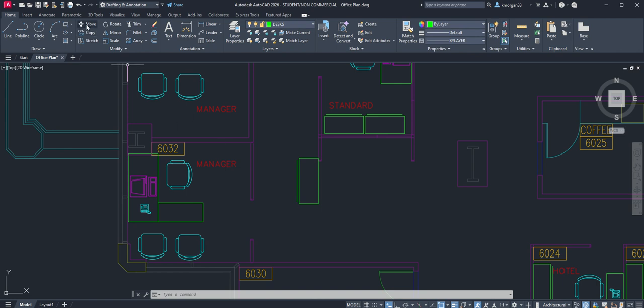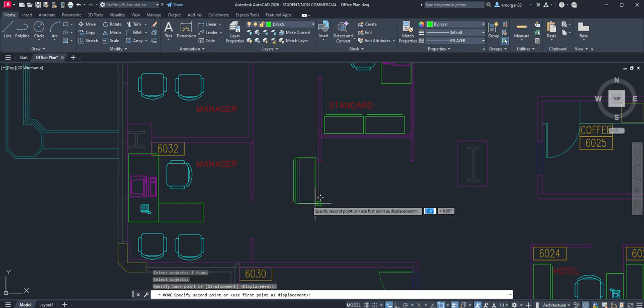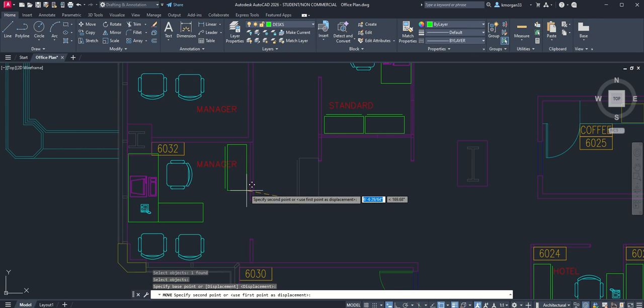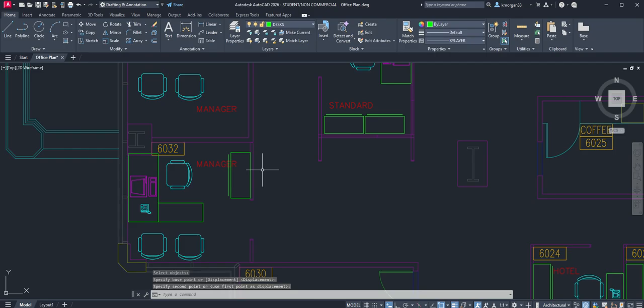And of course let's go ahead and move it. So go there and click on the move command, and it's going to ask you to specify, so we still need to select it, and then don't forget to press Enter on your keyboard. After you finish, your command line is going to change into displacement. Then you can click on that, and we will gently move it and place it right here. So that's where we want to move it.